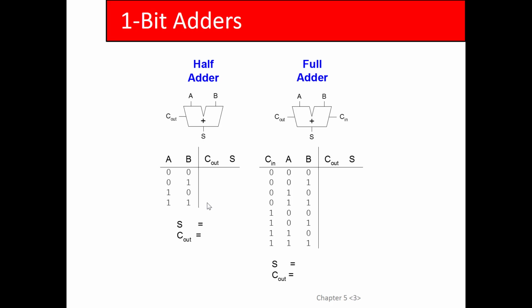How do you do that? It turns out it's kind of complex, especially when you think about performance and how long it takes to do an add, how many gates it takes, and that kind of stuff. So generally you break it down into a simpler problem. If you want to add 2 n-bit numbers, you add each of the pairs of bits in A and B individually, much like when you do long addition on paper, right?